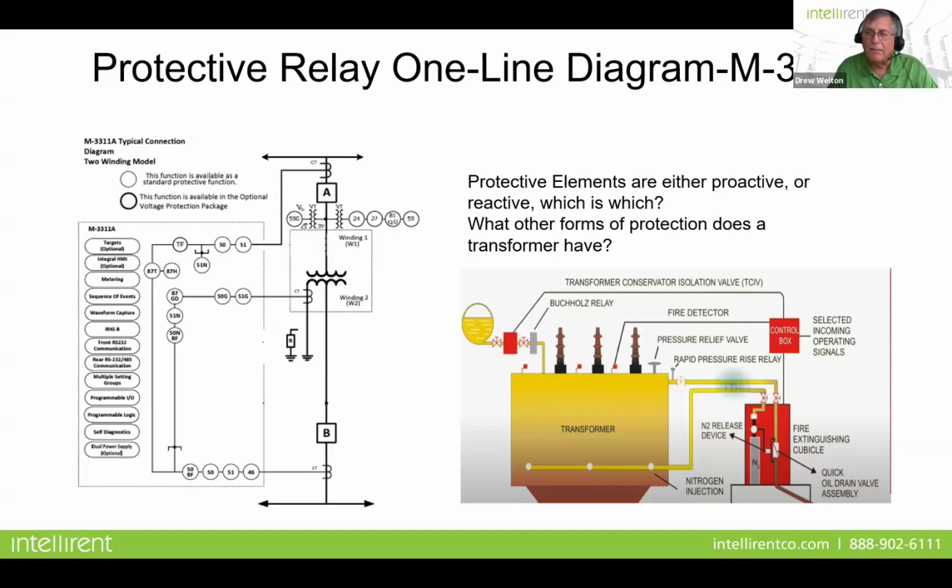Now, the complexity of the digital relays wasn't typically around back in our days, Randolph, as you were referring to, back when a protective element was one relay. For instance, a GE BDD or an ABB HU relay was a single element relay that tripped when it saw an imbalance in the currents between the primary and the secondary sides. Now you've got all these other elements built into one device, and we have to make sure they get configured and tested correctly.